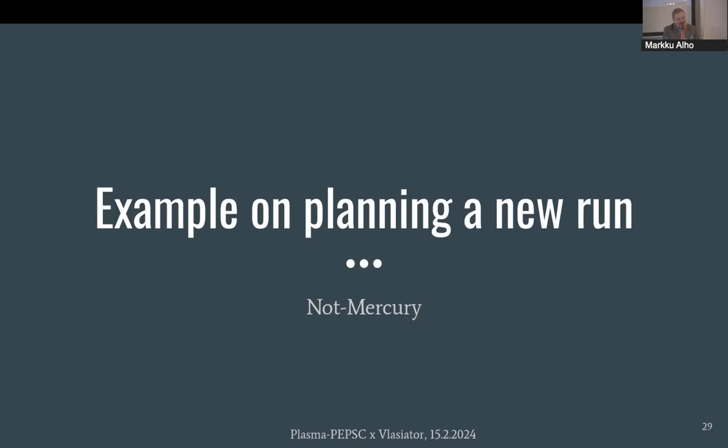That is a very good question. We'll see is the answer. I don't think we have done such tests at least, but that is an interesting point. I don't know if Jan or anyone online has any insight on this. I mean, definitely, one possibility, if you're worried about losing instabilities from the onset, would be to refine the whole box and then see where it coarsens. Of course, you'd have to be careful that it doesn't coarsen the box before your instability rises enough.